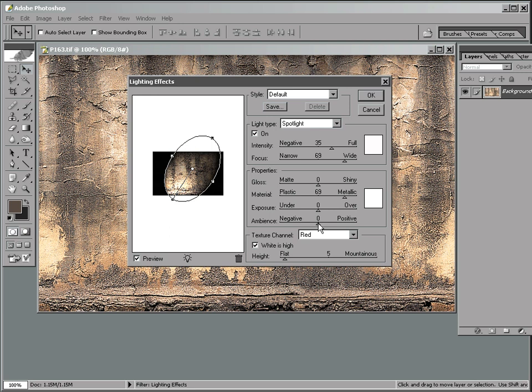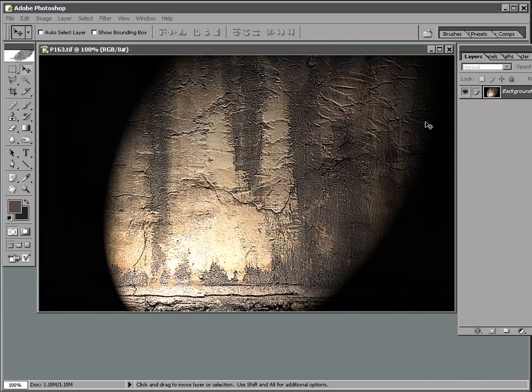The important thing here is that by default, the slider on ambience is set at 8, and if you increase this, it'll provide an ambient light fill outside of the lights, and we want to reduce this down to 0 because this is just piped into a channel in the shader, we don't want to provide an overall incandescence just relating to the spot. So we'll accept this, and we'll save this out now.